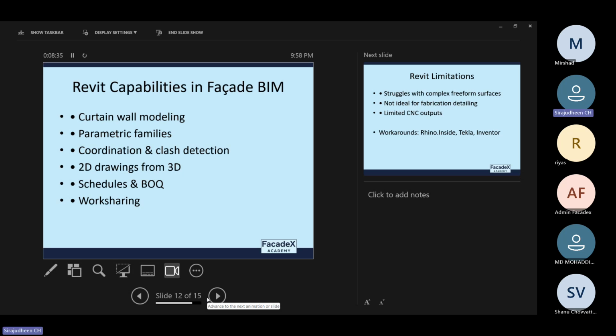We show the grid to back of mullion distance, and we need to show the same on the vertical section also. So in AutoCAD or in 2D drafting, we are doing it all manually. Sometimes even I have found issues like these mismatching in the plan view and the section view, because we are doing it manually. So there are chances of mismatching.